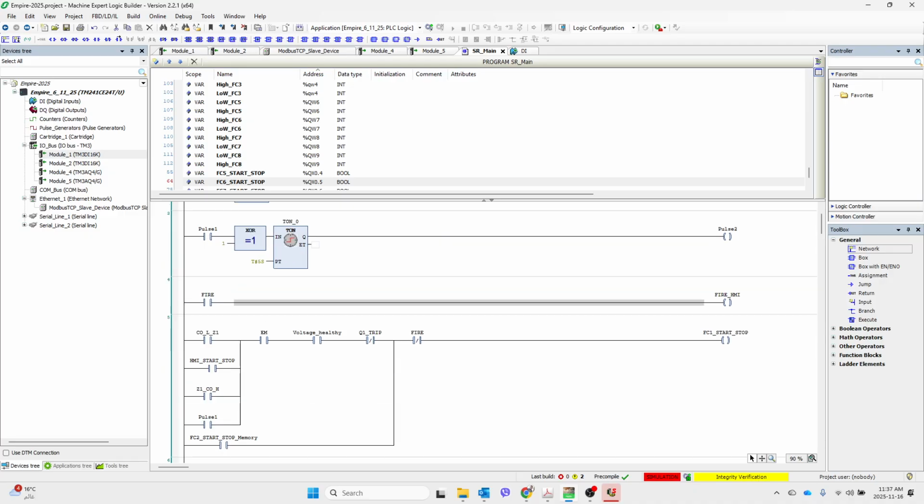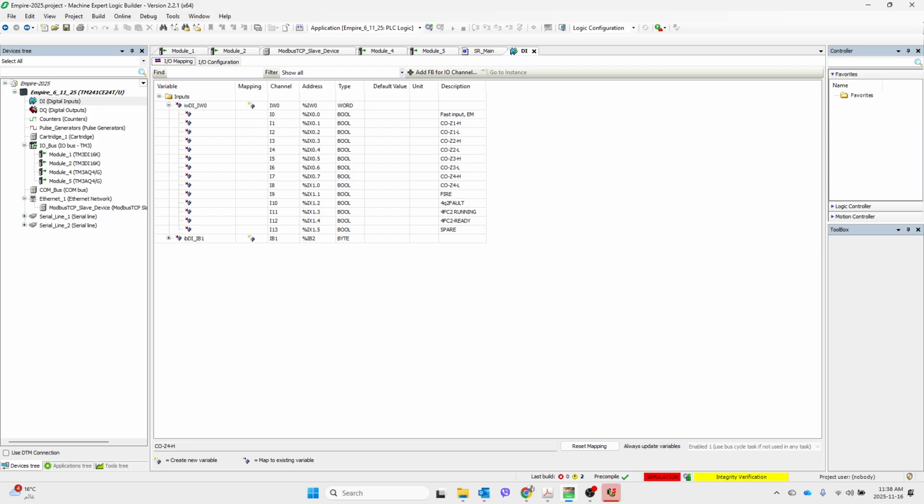Once I have fire, also by the way, I have an HMI connected, so I have to drive all the input signals from the field or the terminal of the device, the inputs, which are coded by %IX1.1. You can see from here. Also the coding of the modules, input module 1.1, for instance, fire.